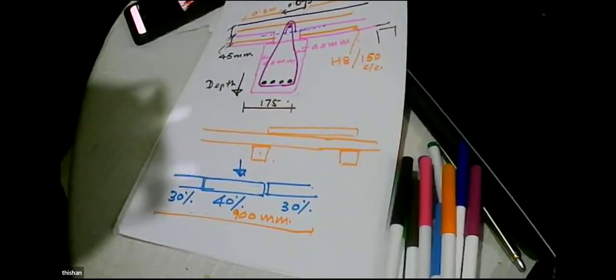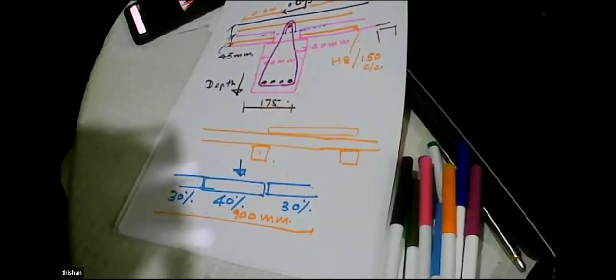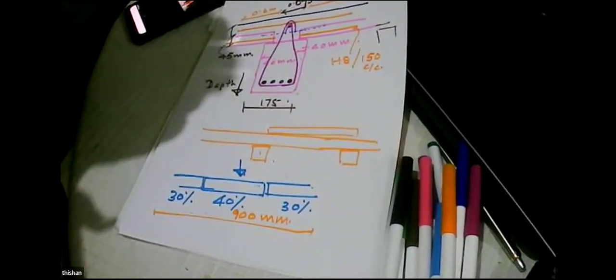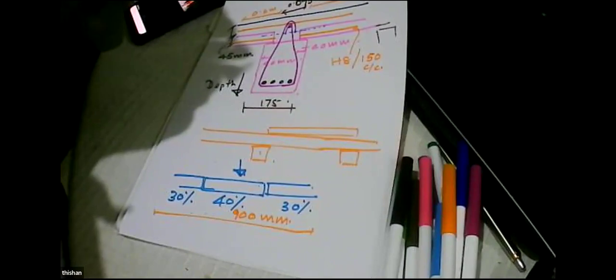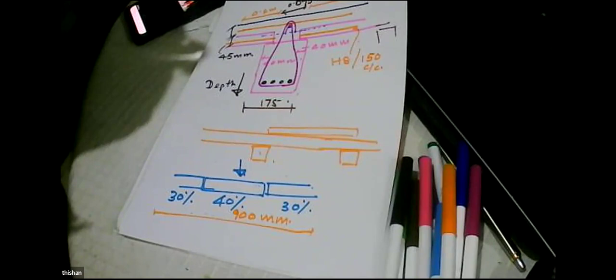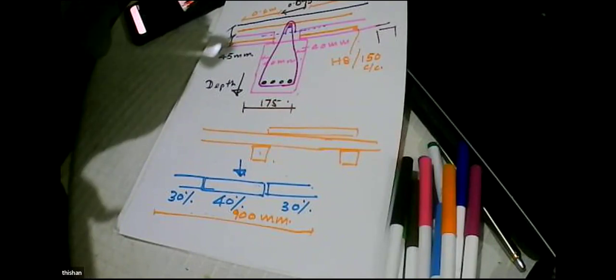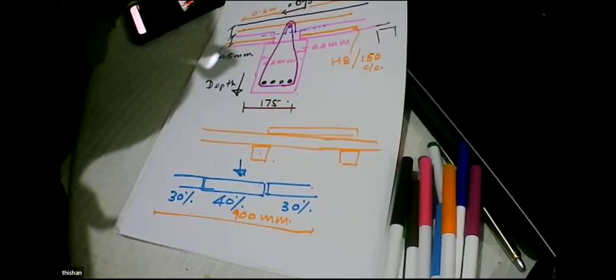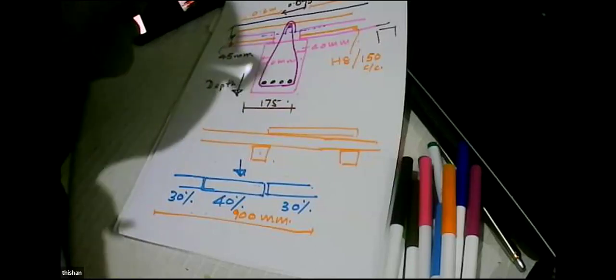Can we use precast slab and beam for washrooms and roof slab? Precast slab is very good because on top of that we have a screed, high quality screed, not just the normal concrete. And because of the design, you can easily have a washroom up to a width of 2 meters with precast slabs.